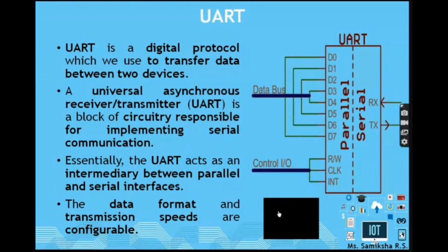So the baud rate is considered and the actual time value or the clock value is calculated, and depending on that we have the data bits coming in and we are clocking in on that time duration, and then it is decided that a particular data bit has arrived, you have to accept it. So this was all about how UART communications are done, that is how serial communications are done.